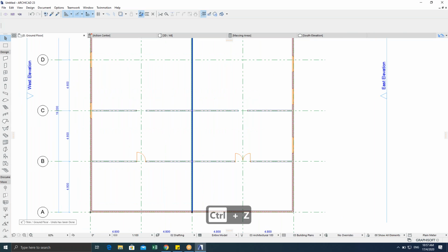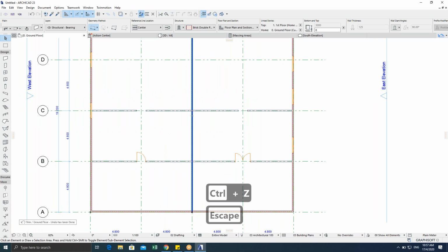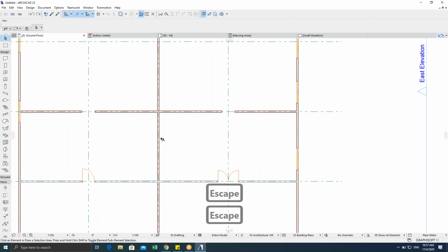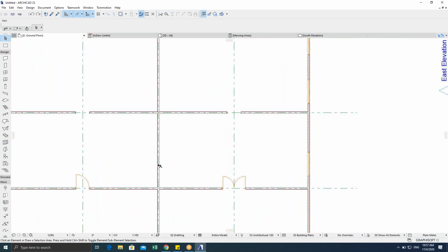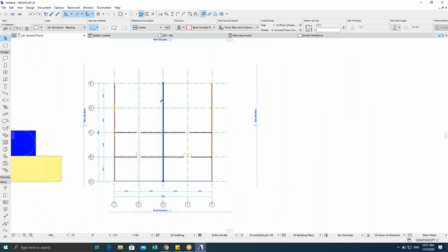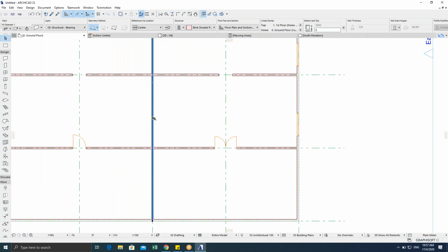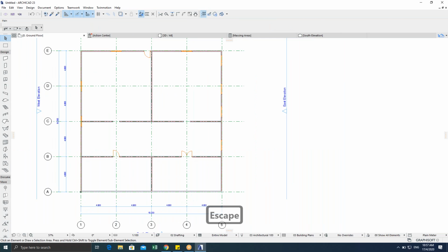Okay, I repeat again. This is like tips and tricks when you do your modeling. Let's say I want to trim this wall only, because now the default one is supposed to be a straight line like that, right? Of course, you can do it manually, put your point here, and after that move again to this, like that. You can cut also, but there is a shortcut to trim your wall.